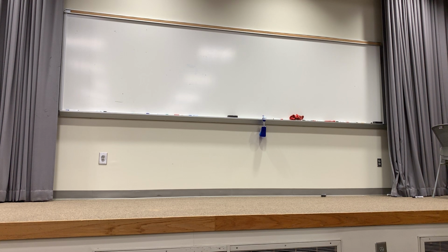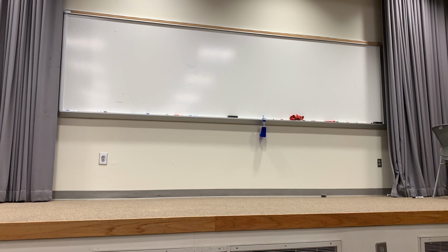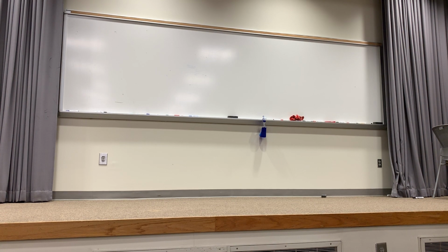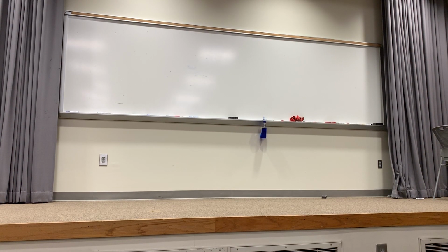Yes? This might be a kind of a basic question, but when you do the redraw, is that just part of these steps to figure out the problem, or is there a key identifier? Well, yeah, the redraw, in my opinion, is important to do, because you could solve each one of those circuits with nodal, or each one with mesh. But usually if you do a redraw, you don't need either. It's super simple. It's either current or voltage division usually. That's the reason I do a redraw, to make it easier to see. But yeah, you could use nodal or mesh for that.